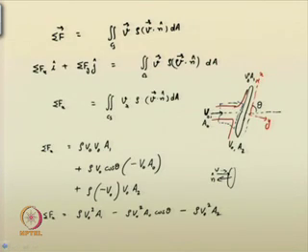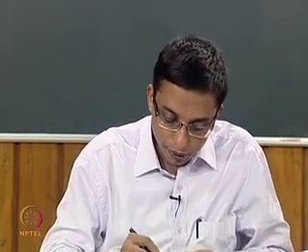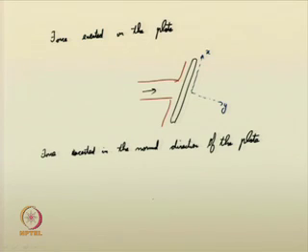We are assuming that in the tangential direction, there is no force component, or sigma f x may be made 0 and all, fine. So, based on those things, the force exerted in the normal direction can be given as sigma f y. It is nothing but equal to the same thing, rho into V y instead of V x earlier, V dot n dA.